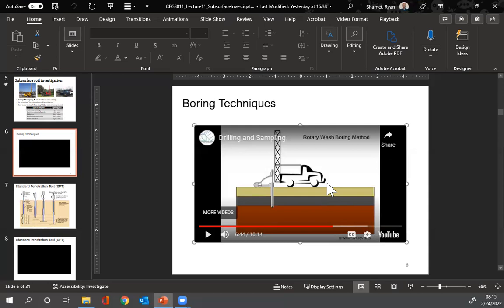So this is kind of the issue that as a geotechnical engineer, you may come across in some of your lab samples. You'll be like, what is this nasty gray stuff mixed in with my sample? Is it natural or is it this man-made added material that's driller's mud? So that's what they're referring to here. But it's just one of the limitations of having to drill below the water table.